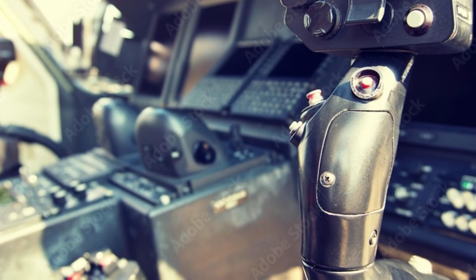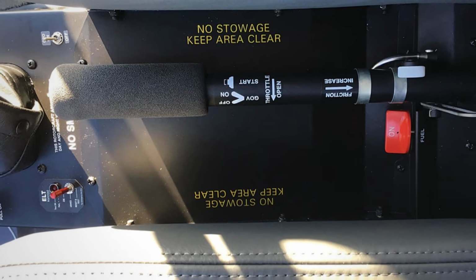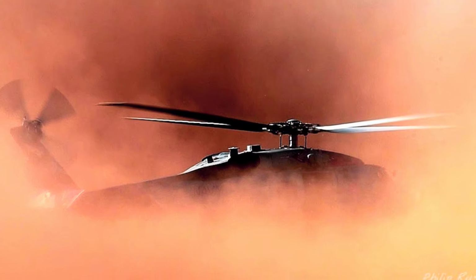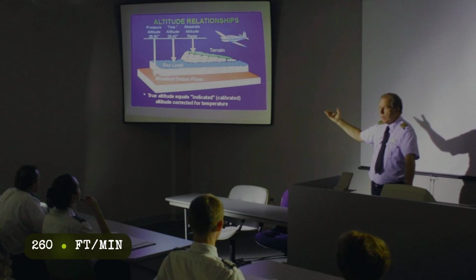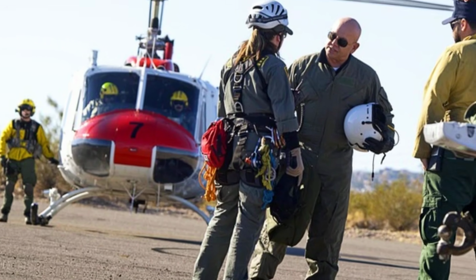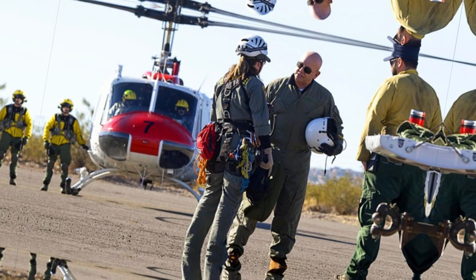The cyclic feels mushy, the collective heavy and ineffective. No amount of added power helps. In fact, pulling more only feeds the vortex, deepening the descent. Training manuals set a ceiling of 300 feet per minute for hover descents, a hard limit hammered in by accident investigations and cockpit voice recorders filled with confusion and alarm.